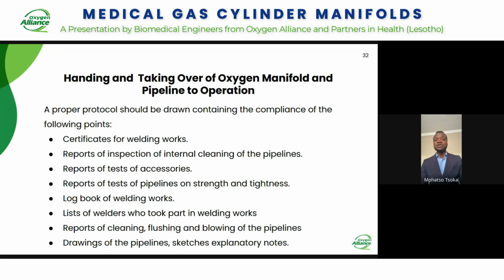And also the reports of inspection of internal cleaning of the pipelines. Remember we said the pipelines should be cleaned for oxygen purposes, and there should be reports that this work was done by the right people, and also reports of tests of accessories, tests of pipelines on strength and tightness, and also the welding works logbook, and the list of welders who took part in the welding works. All these things are done to ensure that the work was done following the standards, and